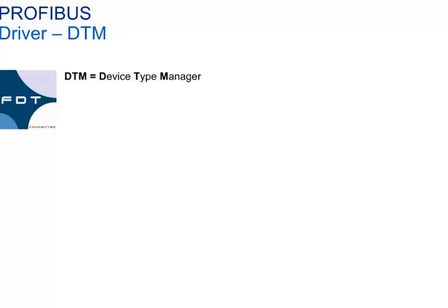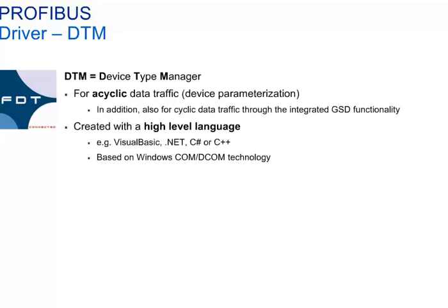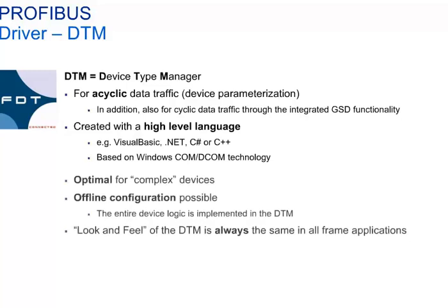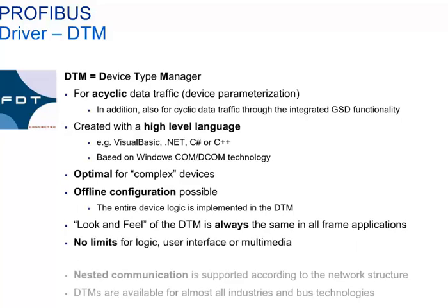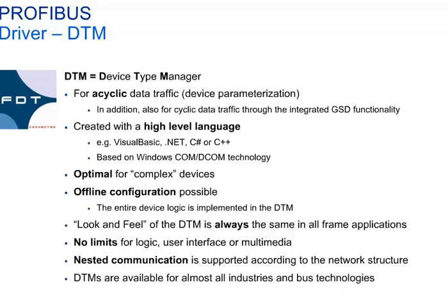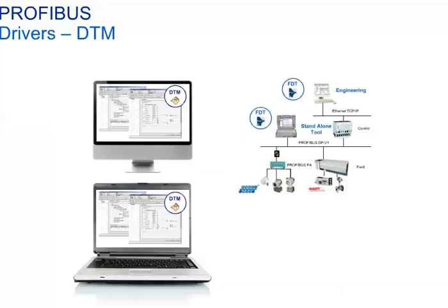The DTM driver is also an option. It is only used for acyclic communication, device parameters, and diagnostic data. Its great advantage over EDDs is the optimization for complex field devices, the virtually unlimited possibilities of the user interface, and the nested communication option.